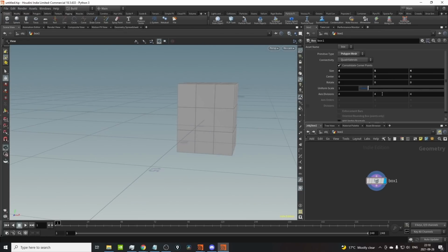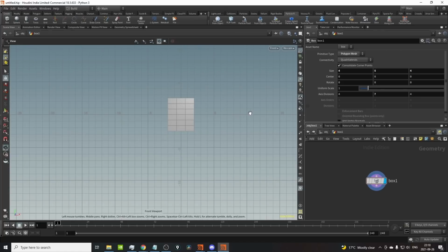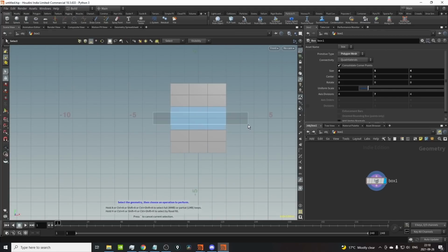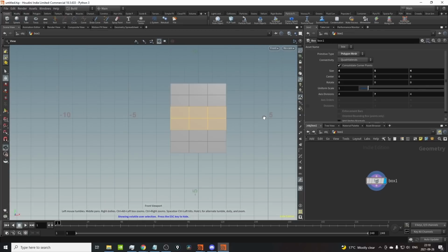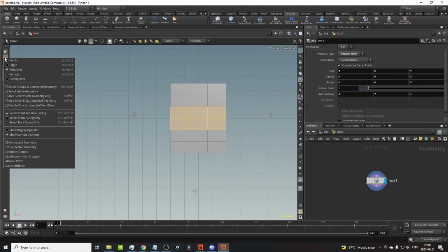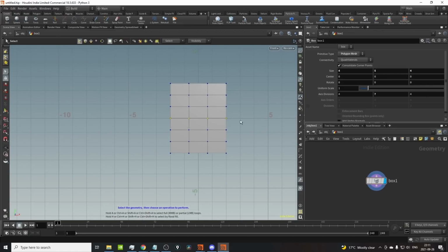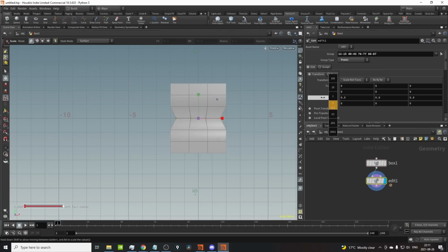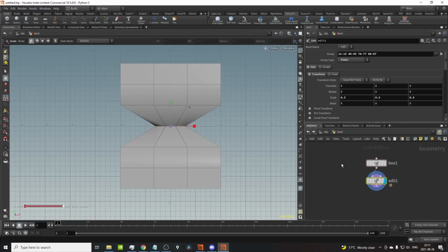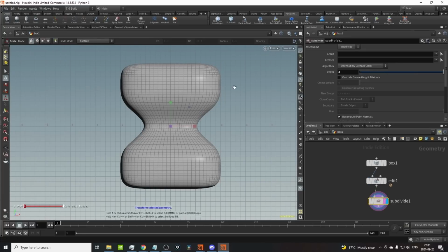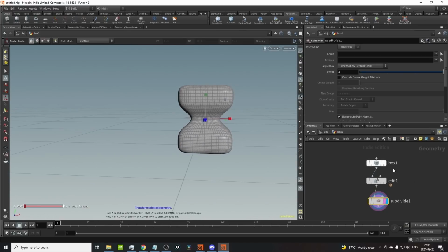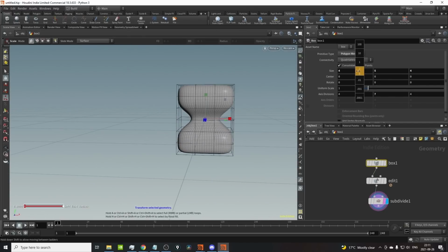Yeah, that's all right. And we'll just subdivide this a few times down the middle. And now we select front view, then select points. Here, we're just going to scale these guys into the middle, making a bit of an indent here, right? And now with a simple subdivision, we can subdivide this guy to be a bit leaner. And we get this little stamp in the lower subdivisions.